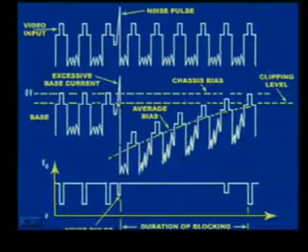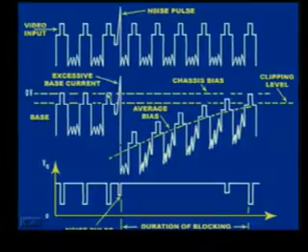The noise pulses, if they enter inside a TV, certainly will destabilize the horizontal and vertical oscillator. If the horizontal and vertical oscillator slip from their original frequency, they will affect the picture formation on the TV screen. See in the figure, a momentary noise or noise pulse which is higher compared to the sync pulse.